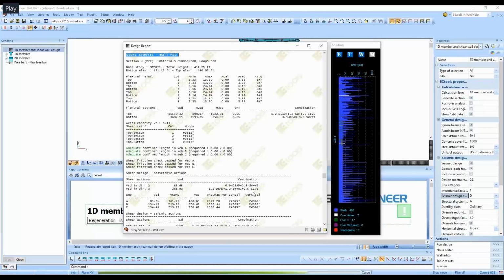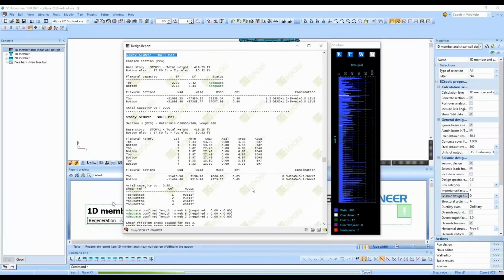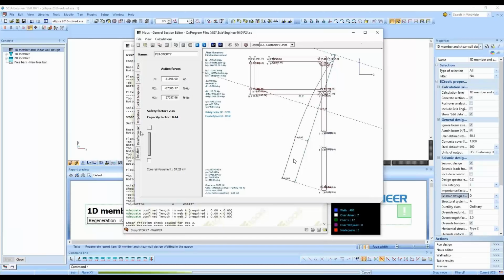After seeing these elements and investigating any issues that one might have, for example, here we see a different core, a very peculiar core shape. These are automatically identified by the analysis model, and they are designed according to the most extreme load case, meaning all load cases are designed, and the one that has the highest reinforcement demand is considered to be the critical. As you see, you have a safety factor for the given reinforcement, or a utilization factor, which is well below 1 for this case.